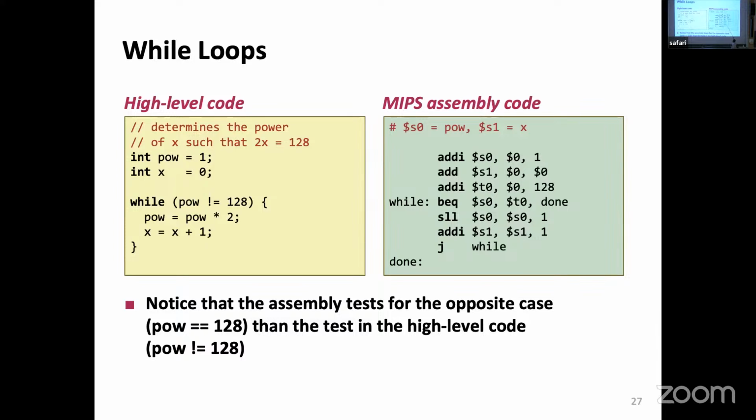And here, what I'm doing is the shift logical left. Somebody was asking me, why do we have an arithmetic left? Isn't the logical left and the arithmetic left the same? They are the same, and this is why in MIPS, you don't have an arithmetic left shift, you only have a logical left shift, because if you're shifting left, both logical shift and arithmetic shift are exactly the same. Somebody was asking the question while we were talking about shift operations a few weeks back.